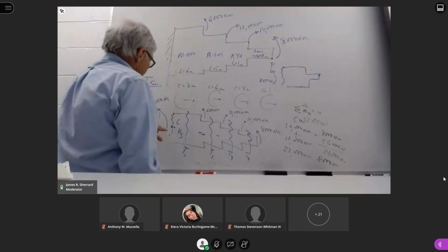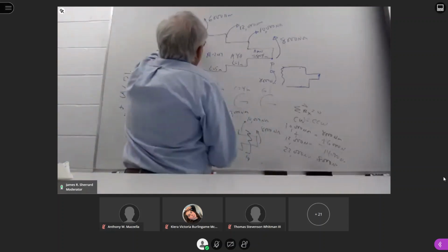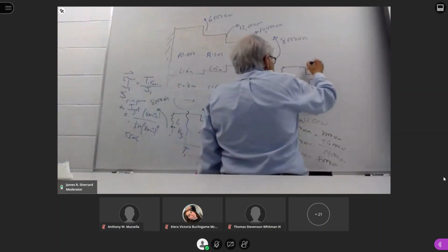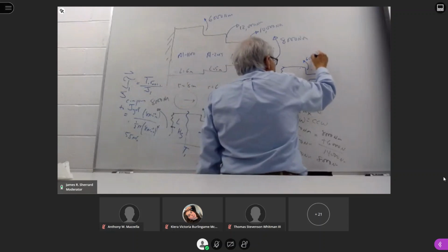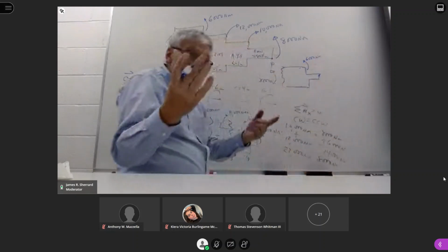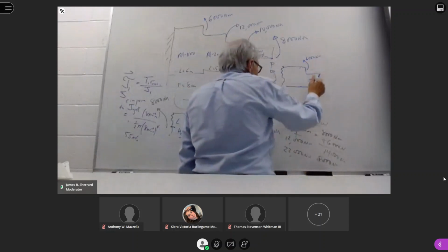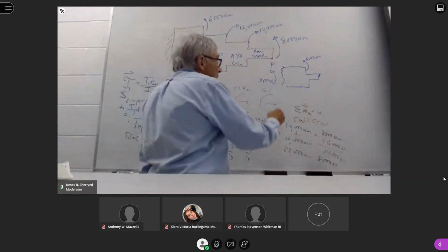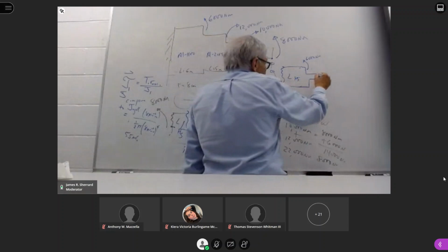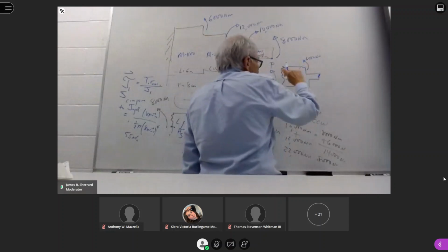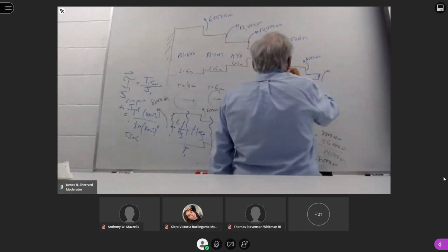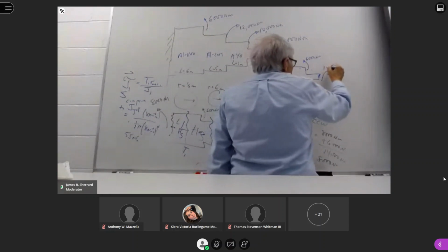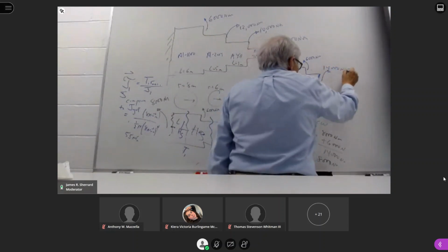So I have 8,000 here on the end. I have this 6,000. One attachment point, because again, we're looking now at the left-hand side. All of these are counterclockwise, so I know my value here is 14,000 Newton meters.